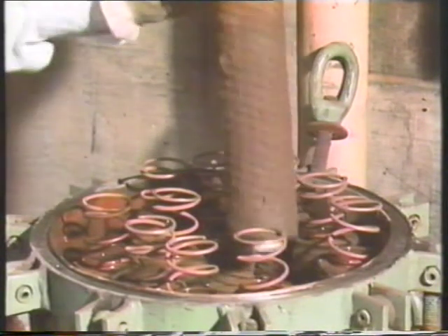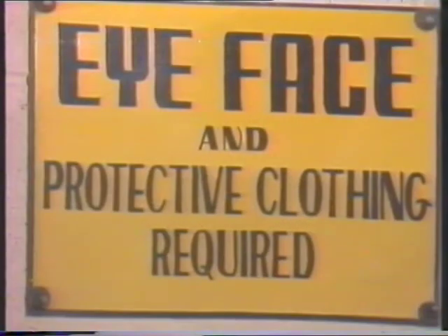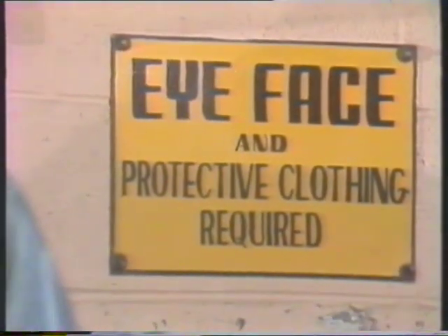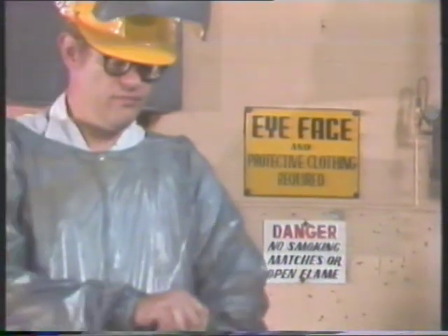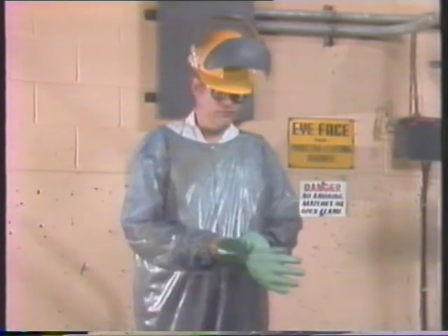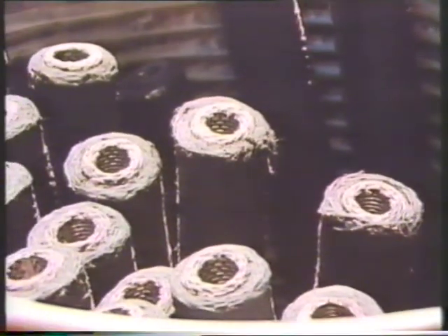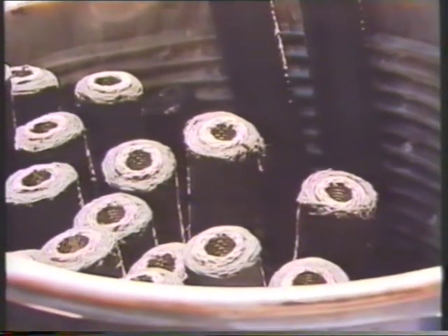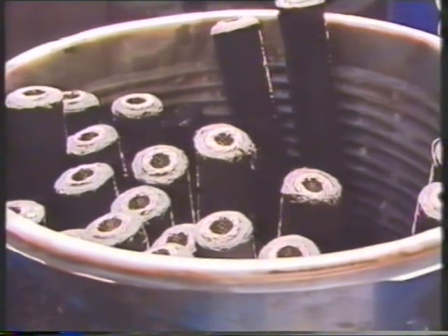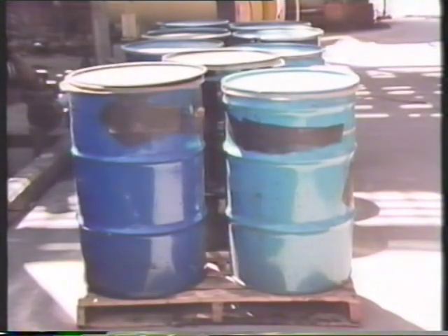Whenever you do change filter tubes, always be aware of any special procedures involved in handling the tubes. For instance, the material being filtered may be flammable or dangerous to touch. In such a case, you should know what specific handling safeguards and special protective gear are needed for the job. Your facility may have special requirements for the handling of the filter cake that remains on the surface of the filter medium. In some cases, the filter cake may be valuable and must be saved for further processing.